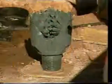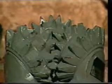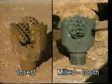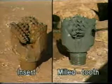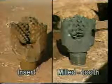The three-cone rolling cutter bit is the most commonly used bit today. The cones mesh together to provide a self-cleaning action, which is furthered by the directed flow of drilling mud from the three nozzles or jets through which the drilling fluid is pumped at high velocity. The teeth bite into the rock, gouging and scraping away the cuttings, which are carried to the surface by the circulating fluid. Rolling cutter bits are distinguished by the type of teeth used, either milled tooth or tungsten inserts, and by the bearings used to attach the cones to the bit body.